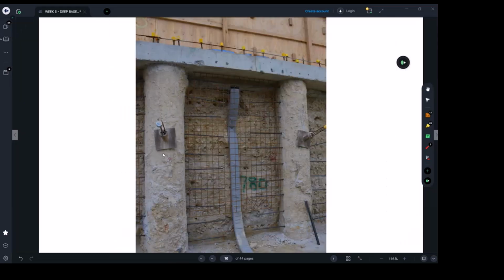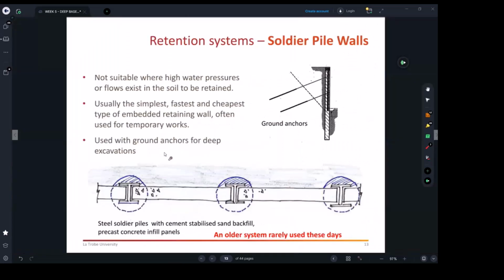Talking about this end here, this end. Yeah, you're going to inject it all the way there, and then they're going to pour concrete because it will help to bond the cable with the soil. Then they're going to tension the cables to make sure it's stuck. And that's what they do for those anchors.